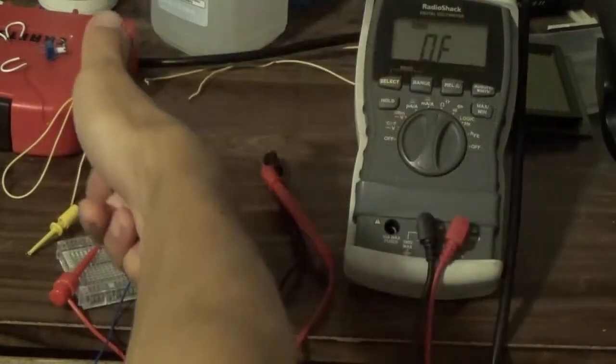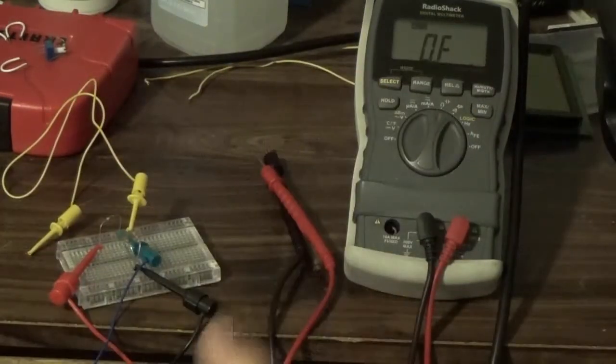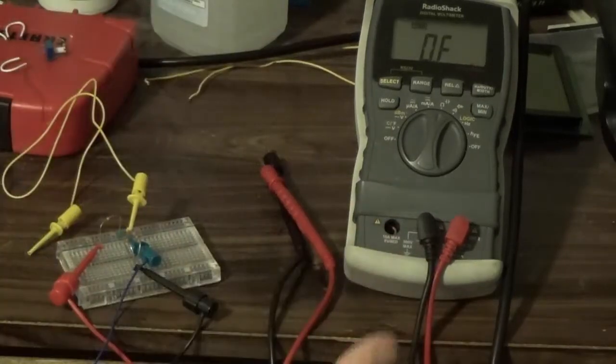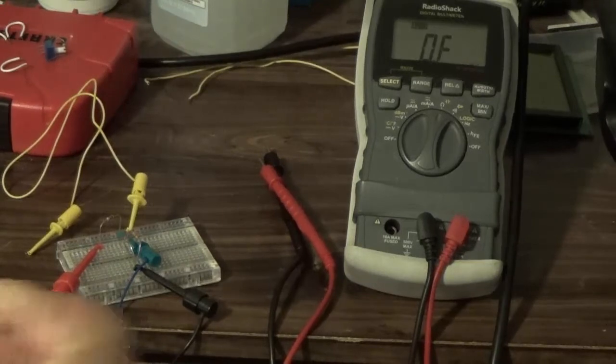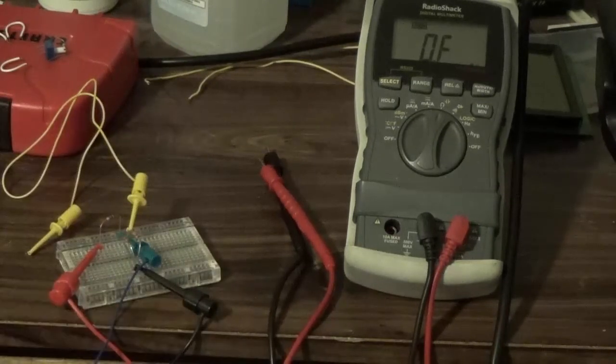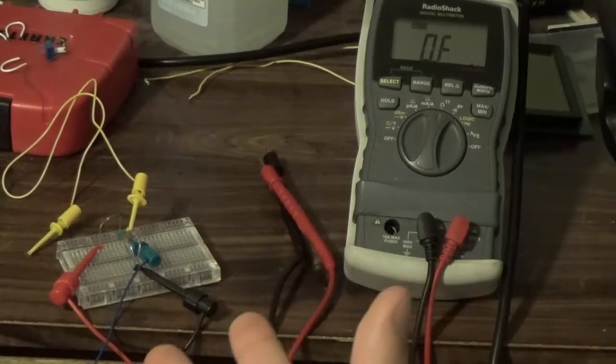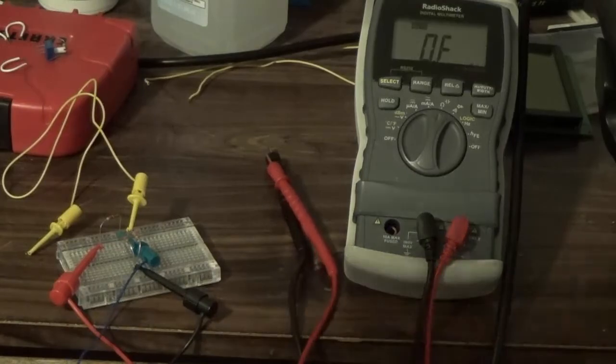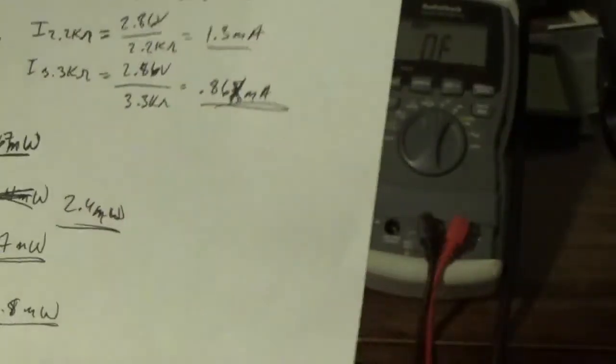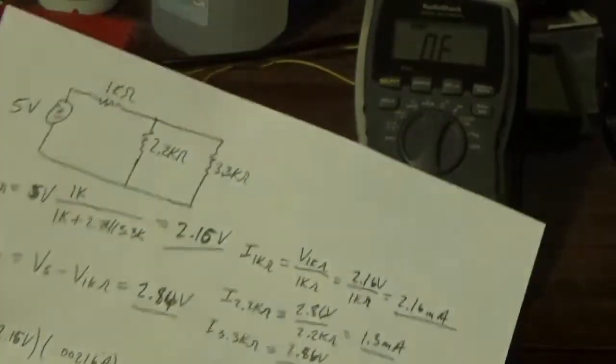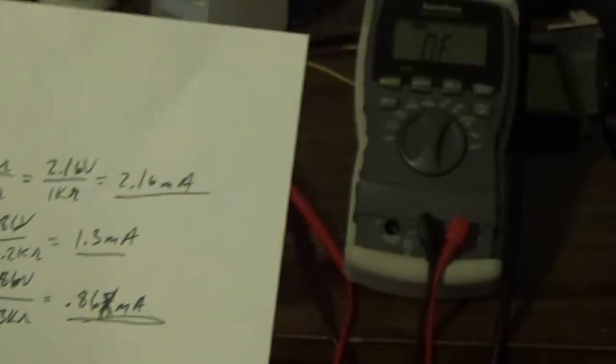So we add that 0.4 ohms into the circuit. All these resistances add up. The power supply leads here have resistances. These IC leads have resistances. So all of that stuff is interfering with our measurements ultimately and changing voltages at certain points and currents at certain points. So, like I said, these are the tolerances we have to live with. So we have to often accept that what we calculate is not going to be exactly what we expect. So like I said, we have to calculate for a percent tolerance.